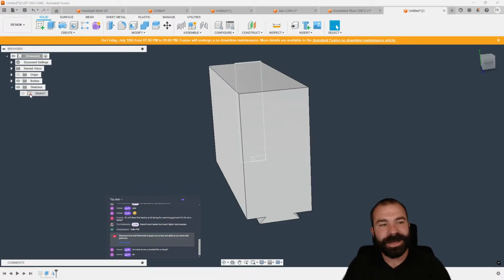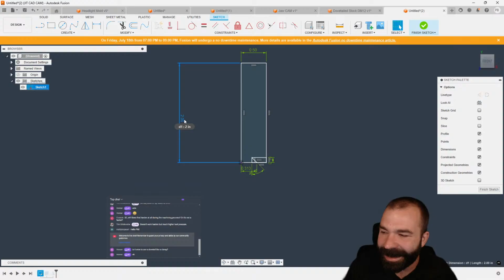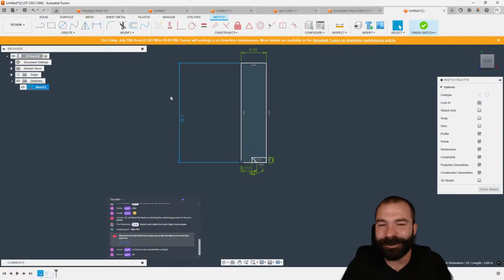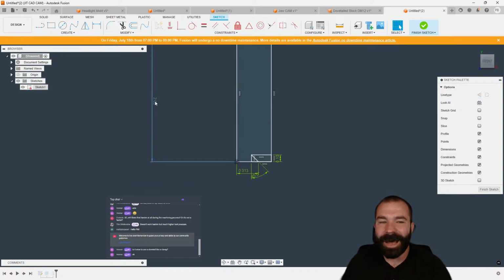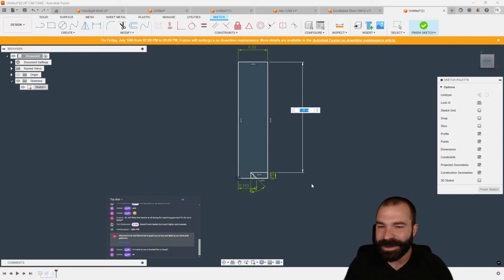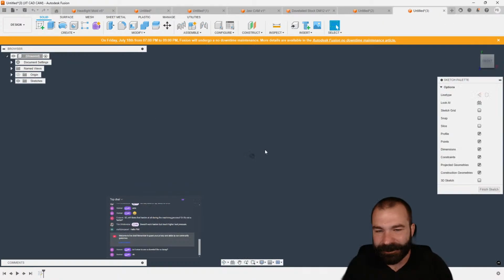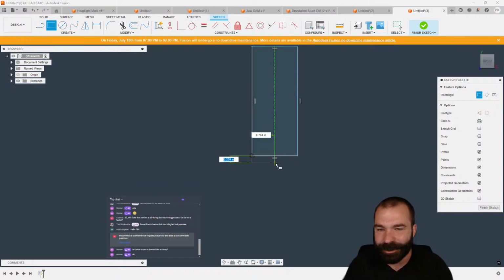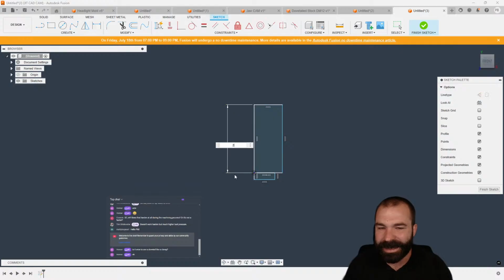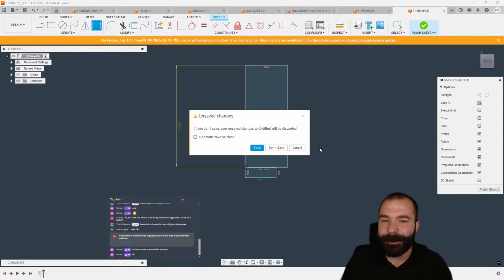And to make sure you guys are thinking, when you create that total height of your stock, right, that you're utilizing it from the correct location. What would happen here is if I would have dimensioned from here up, as you can see, that's a different dimension. Another way I've seen that, of course, is if I start a whole other sketch with the same technique, right? We're going to just use a rectangle up and then you do a rectangle down to create that profile. And then you realize when you dimension this rectangle, you're now forgetting about that extra 100 thou, right? So let's get back to that part.